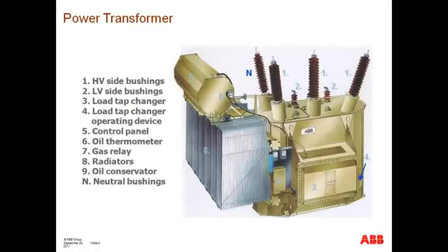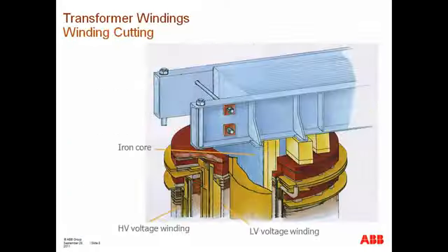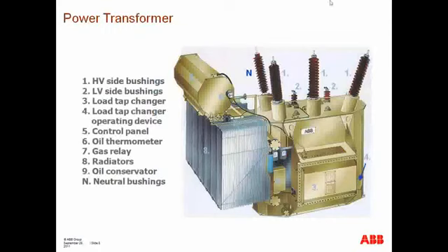And it's smaller because you need a smaller creepage distance because the voltage is less, thus you don't need as much insulation strength, since the voltage of the line is smaller. Here, a couple of other components are important to mention. You essentially have the radiator of the transformer. Usually on some models you just have a radiator, and then there are fans and cooling mechanisms that maintain the temperature inside of the transformer within a particular range.